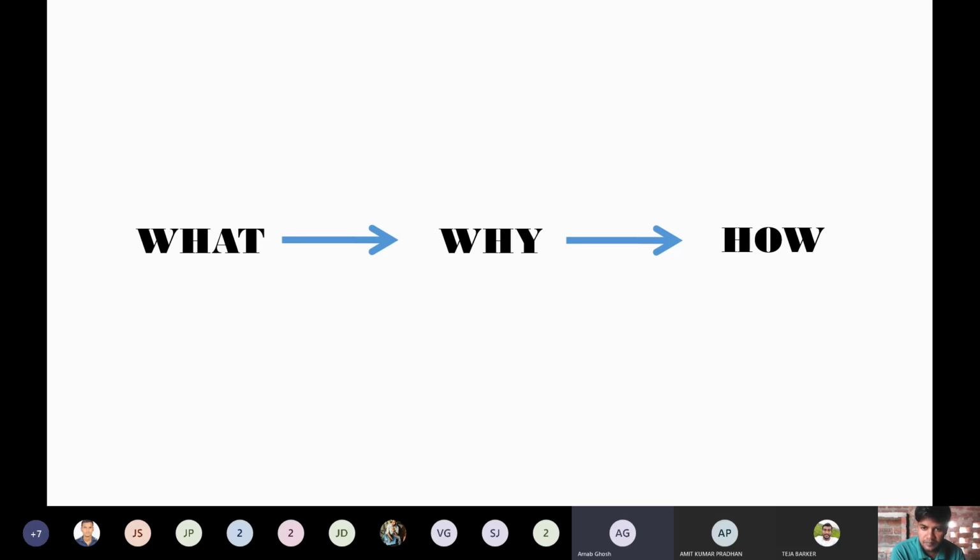It may be single phase or three phase. Another thing: a single AC input to a variable AC with variable frequency. What is that type of device known as? That is called a cycloconverter. Input is AC and output is also AC, but the frequency and magnitude of your output AC will differ, so it will be variable.